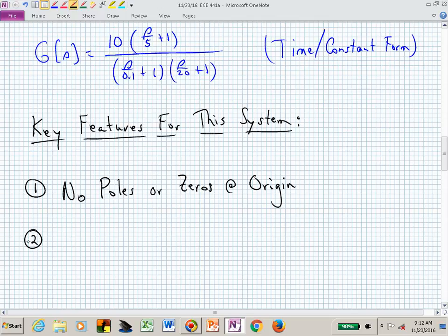What was one part of a system's transfer function that we like to think about in rule 3 in the root locus? Do you remember rule 3? Not cheer 3. I may need to do some cheers today to wake up, but the asymptotes. So what did we focus on with asymptotes? The pole zero excess. That gave us our fundamental angle.